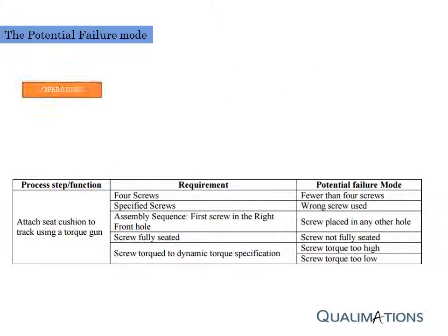Potential failure mode is defined as the manner in which the process could potentially fail to meet the process requirements. A few assumptions shall be made when FMEA is done. For example, exceptions can be made by the FMEA team where historical data indicate deficiencies in incoming part quality. The team should also assume that the basic design of the product is correct.